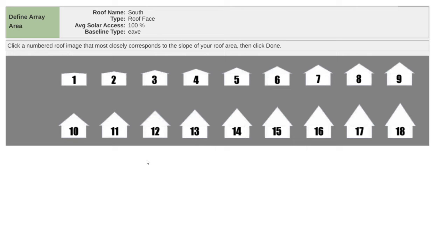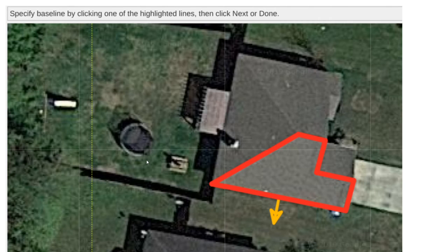So how accurate do these roof areas need to be? It depends. Many jurisdictions require a 3-foot offset from the roof ridges and rakes, which are the sides and the tops of the roof. For structural and accessibility reasons, it is even better to stay 4 feet off the sides and off the top of the roof. This would give the installation a nice margin of error by reducing the need for careful site layouts.